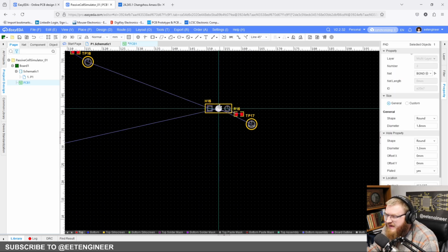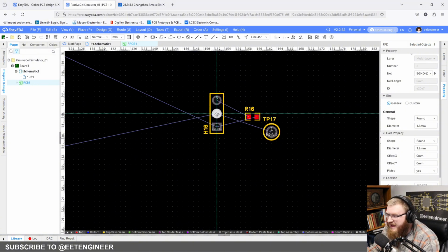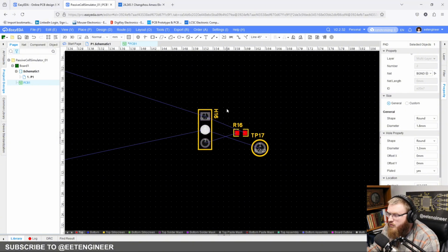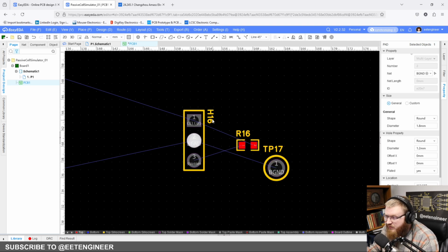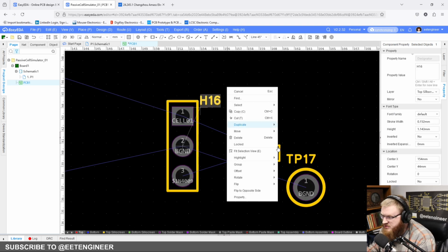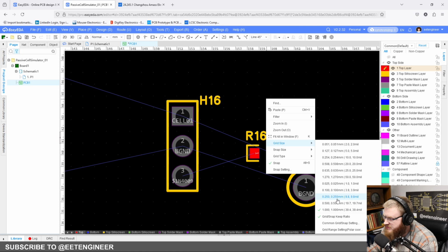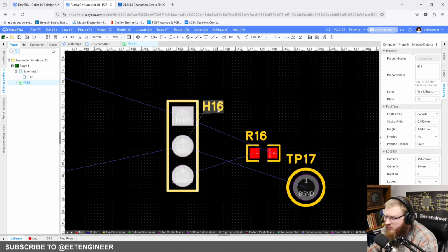But we're going to make this into a nice layout that can be replicated. So you can do a reuse block and replicate the layout. So we're going to do that. We're going to change our grid here to off click. We're going to change our grid size here to 250, so we can have a little bit more control.